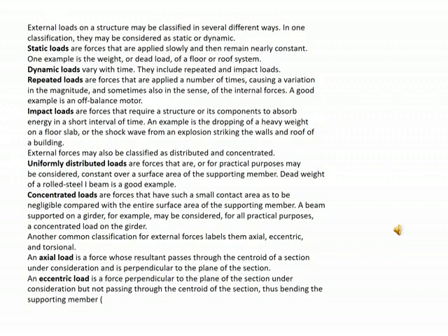Also, the bearing loads are classified according to their nature and source. Dead loads include the material, equipment, construction and other elements of the weight supported by the bearing, including all weight that is intended to remain permanently in place. Live loads include all occupant material, equipment, construction and other elements of the weight supported by the bearings that will likely be moved. So we say live loads.